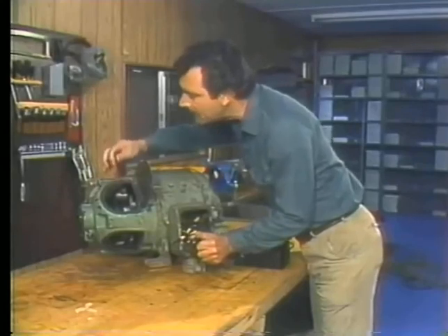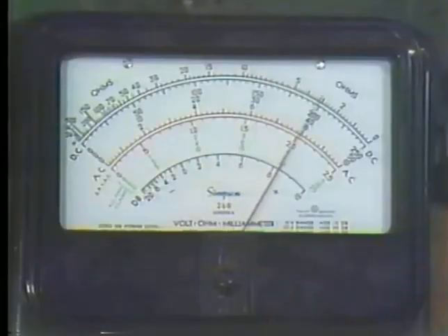Let's change the lead to the other holder. Okay, we do get a reading here. That means we're on the right brush holder and that the series field is not part of our problem. Did you notice the difference in the readings? High reading for the shunt field and low reading for the series field, just as we should get. But we aren't completely through with the series circuit yet. If you think back, you'll realize why. We only eliminated part of the series circuit, up as far as the brushes. We said these brushes can be trouble spots in a DC motor, and it's true. You'll find that they're worth checking.